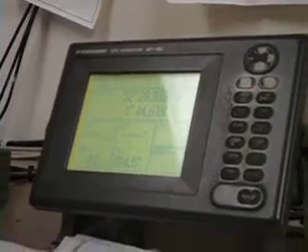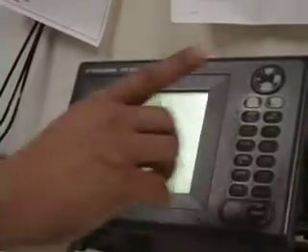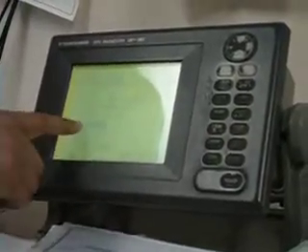Demonstrate how you would disable a satellite and state under what circumstances you should do this. So when will you disable a satellite and how to do it? Go to main menu, number 9, system setting, number 6, GPS setup. Now here is disable satellite, highlight that one.